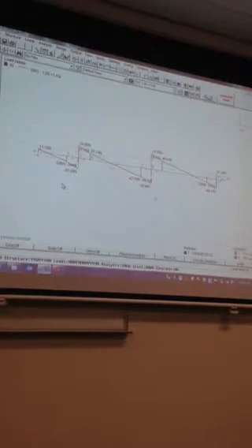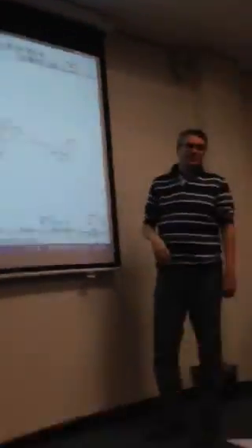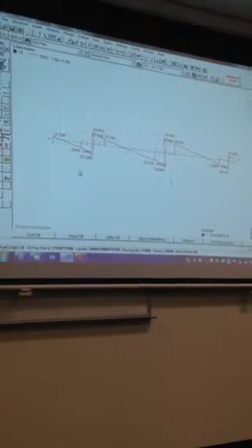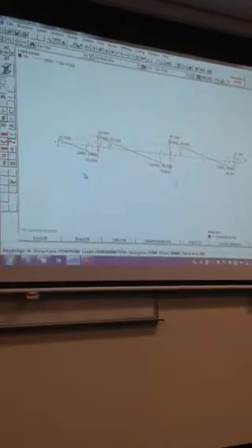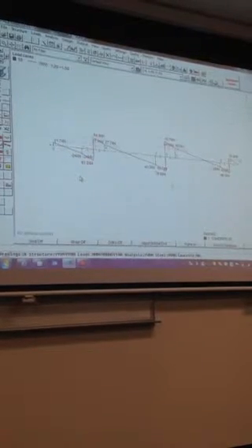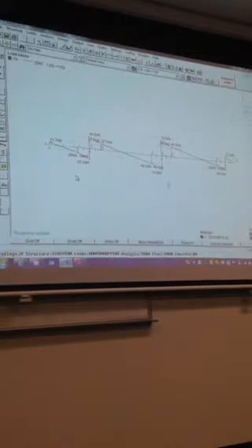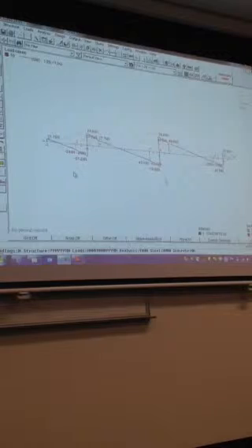And if you satisfy for 49.5 without any ligatures, and you shouldn't need ligatures in a slab, if you do, you've made a mistake, then basically that applies all the way through. Because if we're designing for the maximum bending moment and the maximum shear force, and we've satisfied those requirements with concrete alone, it's all pretty sweet. We don't need to worry about looking at anywhere else. All right?